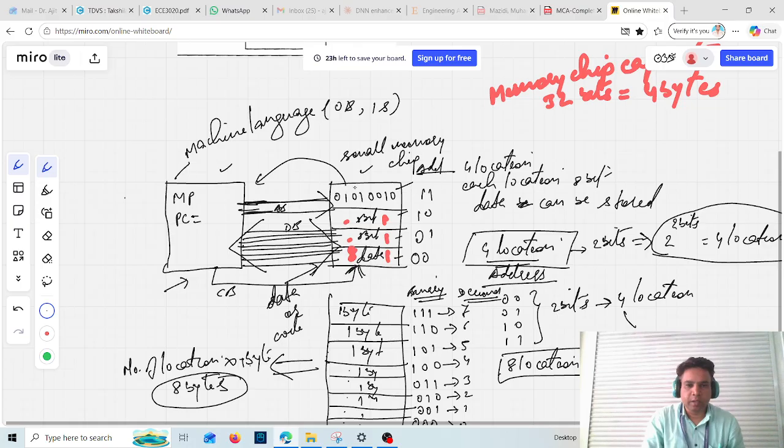Right now I'm assuming that this is constant data. This constant data is residing in which address? 11. So this address 11 will be stored by the PC register. The PC, as the name suggests, keeps counting the next address from where the data has to be fetched. This PC, which is storing the address, will be loaded on the address bus. So there are two electrical buses here.